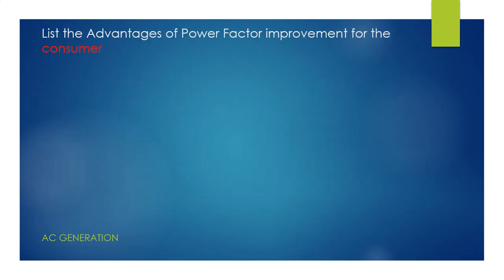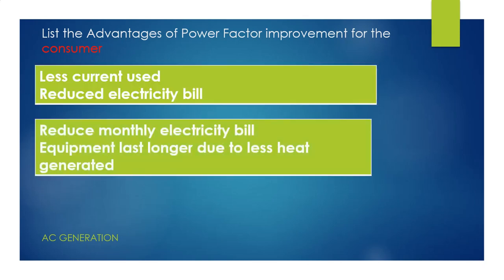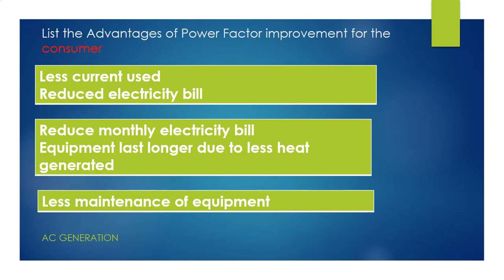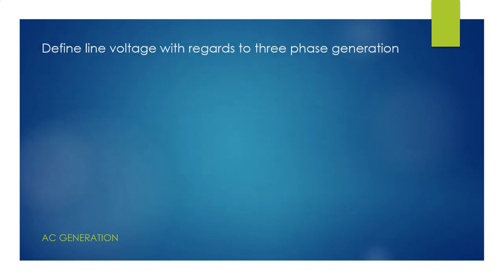List the advantages of power factor improvement for the consumer. Less current used, reduced monthly electricity bill, equipment lasts longer due to less heat generated. Less maintenance of equipment.